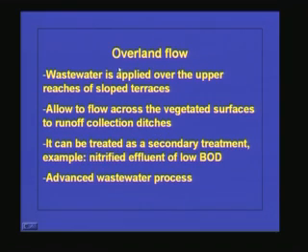Now we will see overland flow. What is happening in overland flow? Wastewater is applied over the upper reaches of the sloped terrace, allowed to flow across the vegetated surface to runoff collection ditches. So it can be treated as a secondary treatment. For example, some degree of nitrification will be taking place if the BOD of the wastewater is low, and advanced wastewater treatment can also take place. The reason is the soil will be acting as an adsorbent, so it will be taking care of most of the other organic matter present in the system.